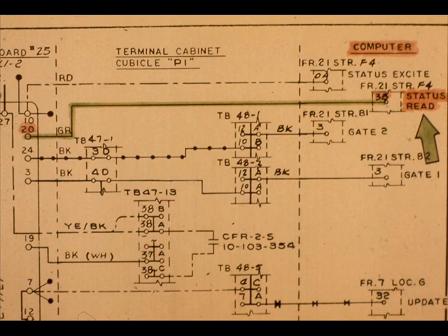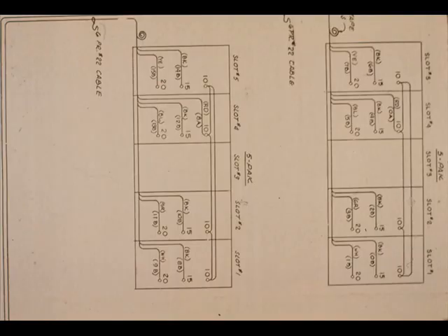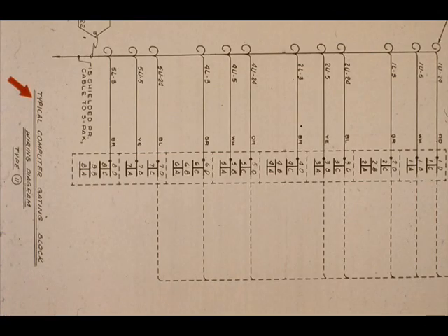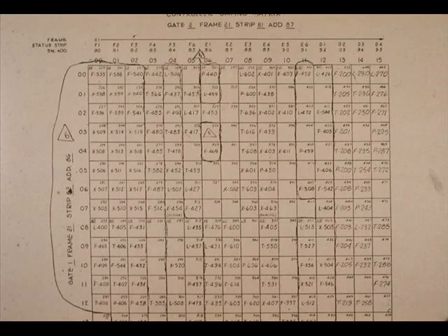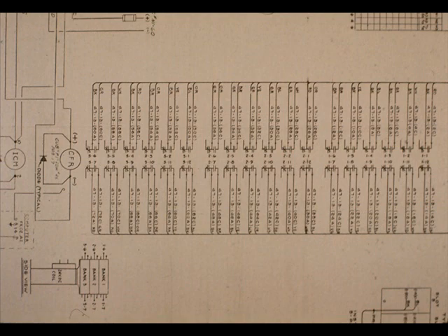For instance, the loop diagram tells you status read is a green wire. This means little if you want to find the wire so you can test and terminate it. A status sense wiring detail and schedule should be used. A matrix gating jumper schedule should be used to complete the gate 1 line. The computer gating block wiring diagram should also be used. And a computer fail relay drawing should be used to wire the CFR circuit.